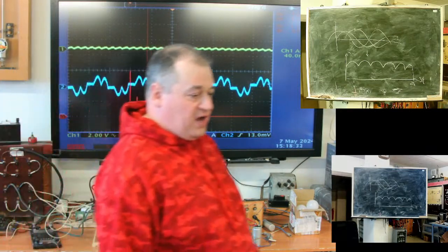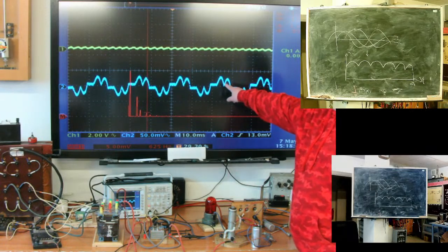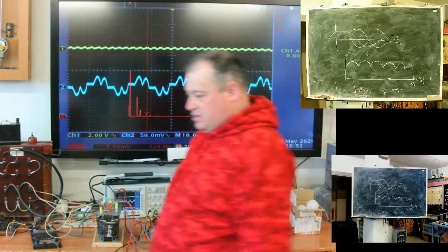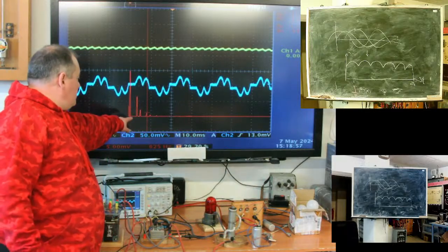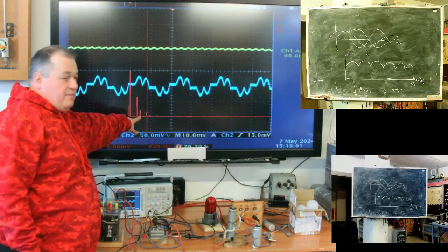With three-phase rectifiers, if you have a star-star connection, you will see not a single wave like single-phase rectifiers, but you will get this double wave structure containing a gap at the third harmonic. This is number 5, this is number 7.